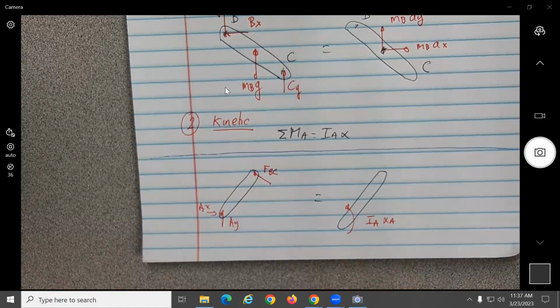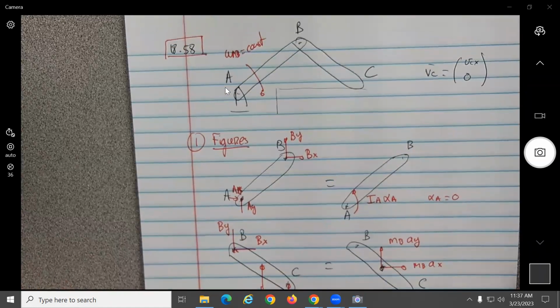Yeah. So I understand why we don't do mass for the first figure. For the second one, is there a reason on the motion? Is there a reason why we don't also get the moment of inertia? Okay, I didn't understand your question. I don't want to interrupt you, but on this one, what is the motion of bar BC? Translation and rotation. So there is no single point, unless you go and find that there is a single point where the motion is only rotation, no? So on that one, you're going to need the weight no matter what, because you're going to have to do the m a_x and the y. Was that your question?